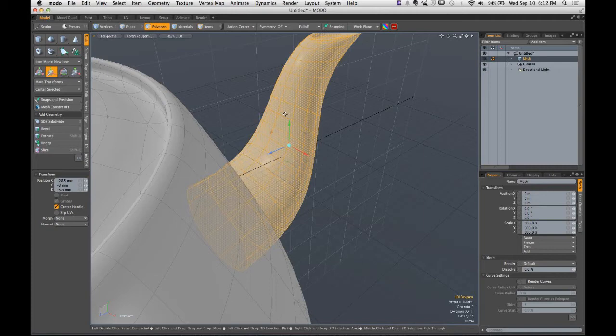Now, what is the tip that helps us understand which axes we're going to be transforming this object along? The color. What is it about the color? The color of the circle corresponds to the axis. Bingo. There it is. The color of the circle that we choose represents the axis that we're not going to be moving this object along. So if I was to pick the green handle, which axes am I going to be moving this object along? X and Z, the red and the blue. Okay.